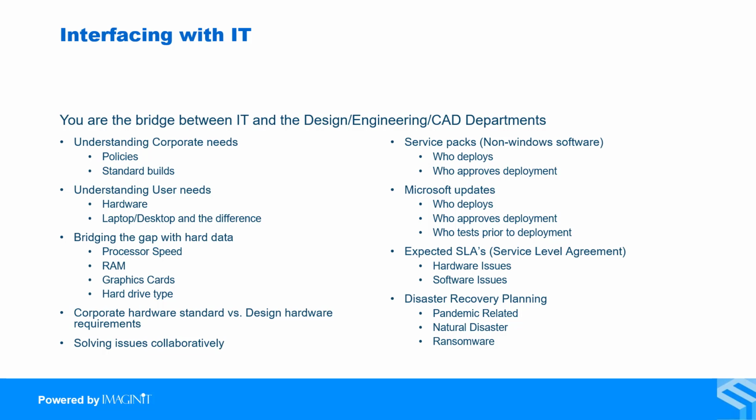Other updates means that if you're planning a deployment of an update, you need to make sure for things like Revit and Inventor that everyone gets it at the same time. Because if you have multiple users that are using Revit 2019 at different patch levels or different update levels, you're now creating a situation where you can introduce errors into your models and cause problems.